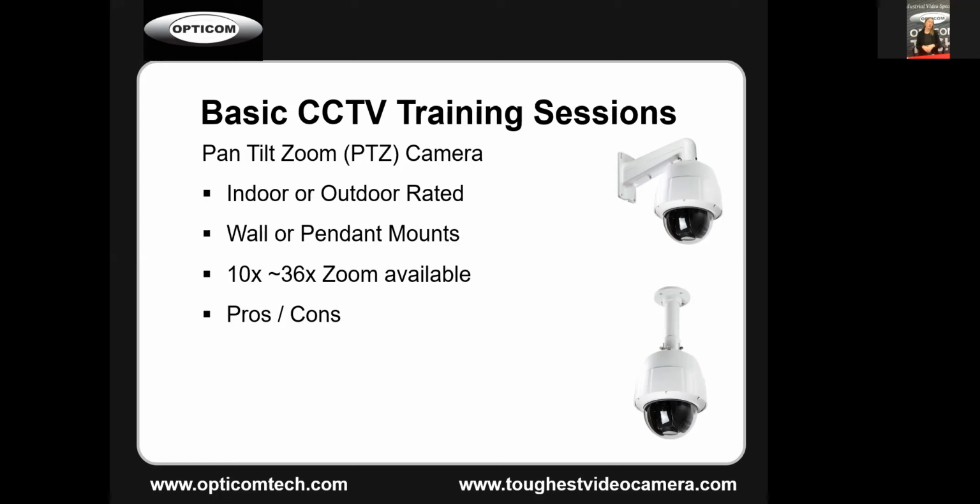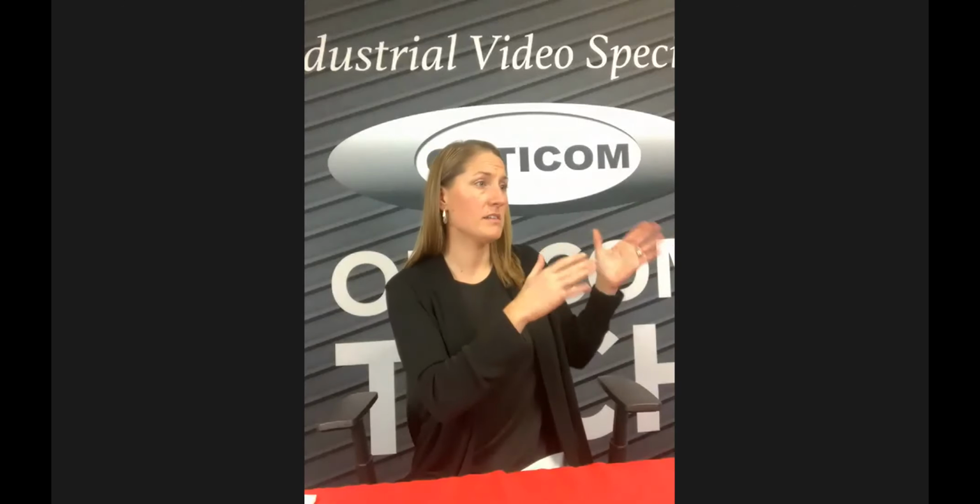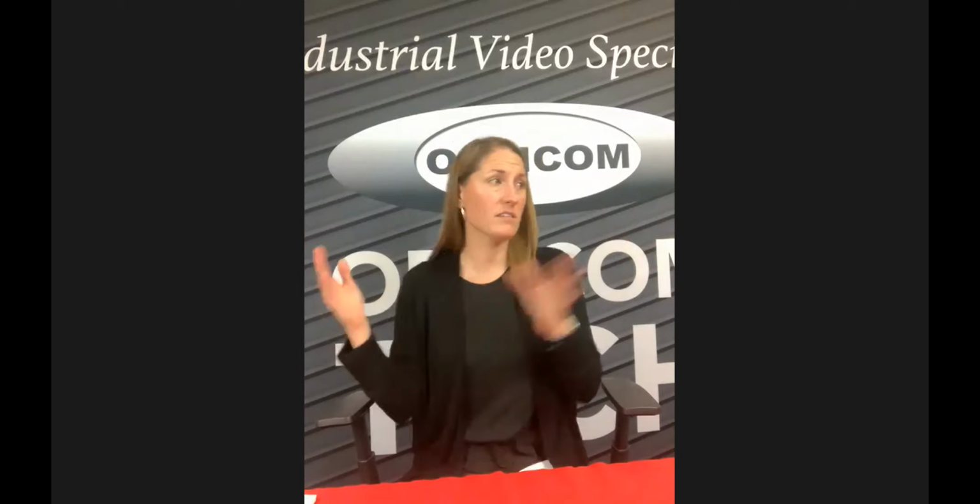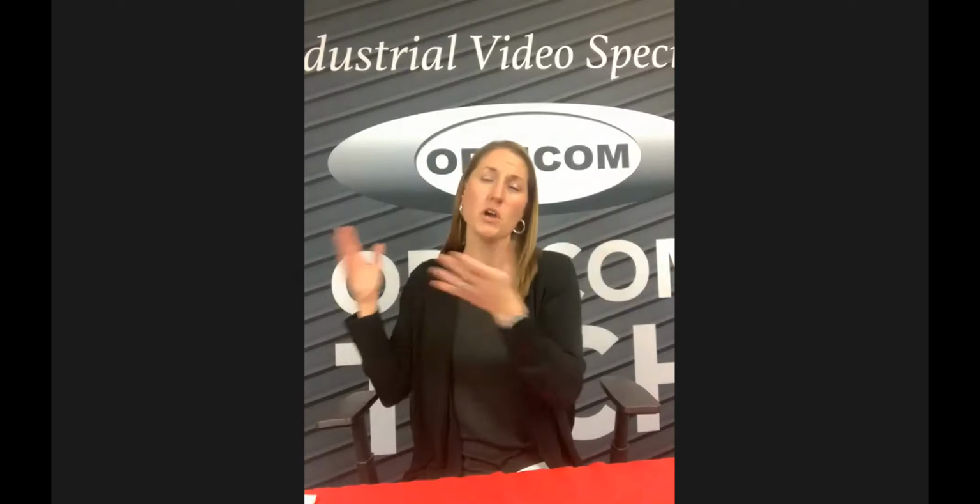So a lot of people are like, oh, I just want to do a PTZ. Well, if you're using a PTZ for security purposes, and the camera is looking that way, and someone is breaking in on this side of the door, that PTZ camera is absolutely worthless to you, right? Because it's looking over here when the action's over here. So there's definitely pros and there's definitely cons to it. And you just need to determine what is the best fit for that application for yourself or for your customer, whatever it is that you're working on personally.